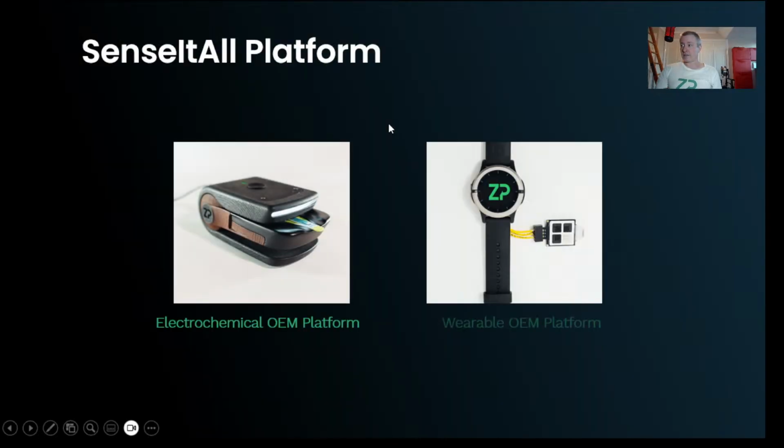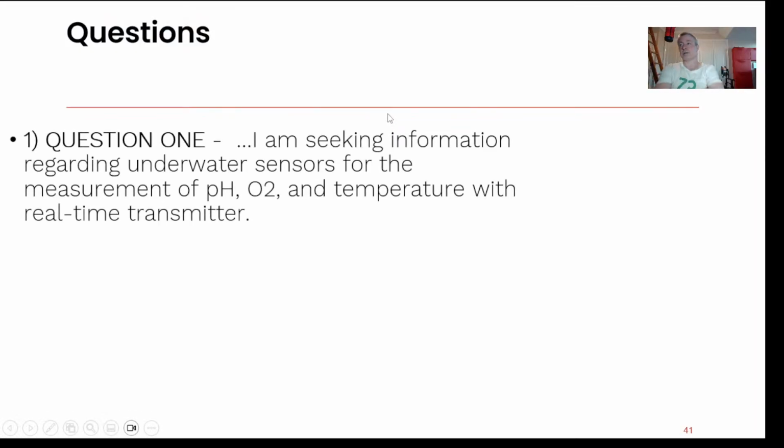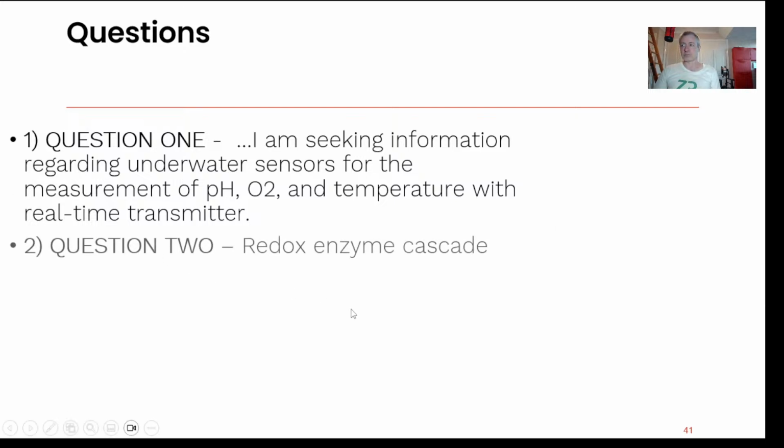So I think I'm coming up to the end now, so I want to just be efficient. Right, so question number one. I really appreciate you coming on this evening, Sahand, so thank you. But for us to do pH and oxygen in a continuous manner, we're not ready to do that. We could do it, but it's just not going to be good. pH sensors today drift, oxygen sensors drift. People will want low cost, they want calibration free, they want cloud connectivity. You can have cloud connectivity, but it's the drift and the repeated calibration that's going to really upset people. So we don't want to do it unless there's a really good budget in place.